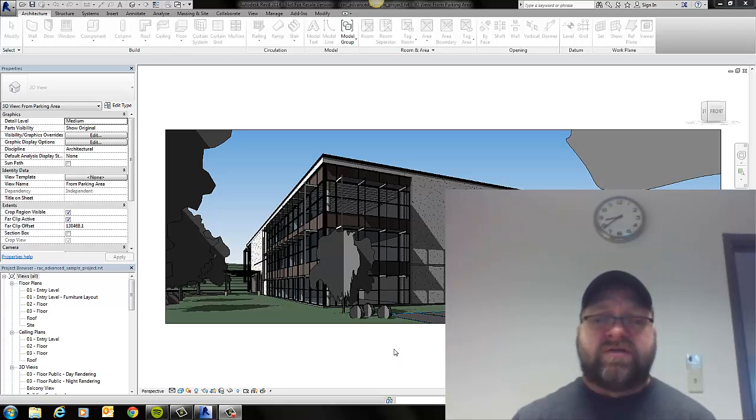So this layering system becomes a method that you can group items together that are similar, or you want to have the same color, or you want them to print with the same line weight, or you want to be able to control their visibility. A variety of reasons for grouping things into a layer and saying all of these things belong to this layer, and you give it some name, and then you have some kind of control over what that layer does and what it doesn't do. This idea of organizing things into layers happens in Illustrator or Photoshop. That same metaphor happens in lots of different programs, because it's very easy to understand.